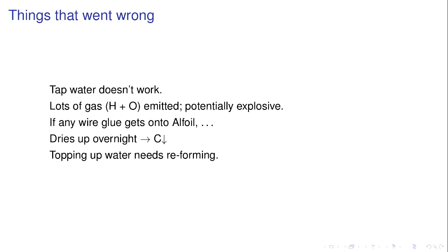If you accidentally drop a bit of the wire glue onto the alfoil and that gets into your electrolyte, you've got a dead short and nothing's ever going to happen. And that wasted me 2 days.